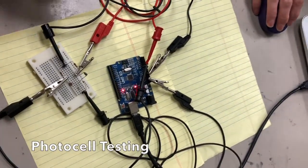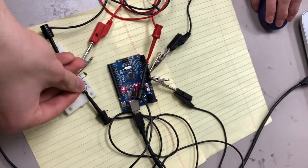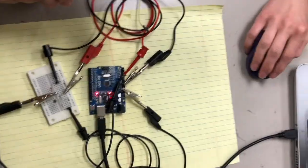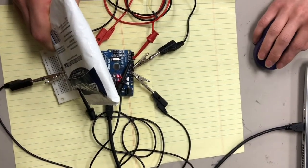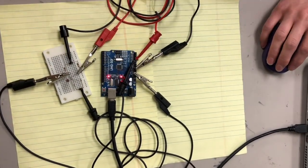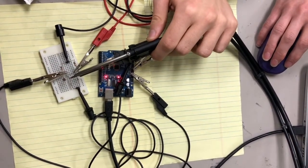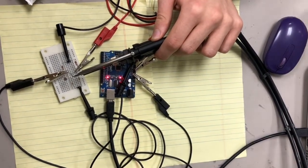This is the part where we test the photocell, where we test it in dark conditions by pinching it to provide no light, and then providing a light source to see the resistance change when light is applied. Now we're testing the thermistor to see how the resistance changes when we apply an ice pack to test cold temperatures and bring it to 0 degrees Celsius, and then add heat by using a soldering iron to bring it up to 100 degrees Celsius. You'll see in the following graphs these resistance changes and the temperature calculated with MATLAB.